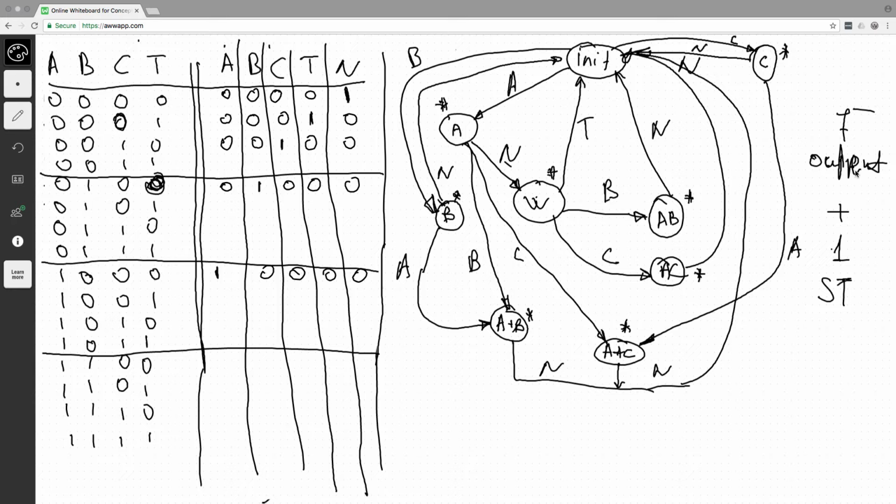And it actually depends on the implementation of the timer, because timer expiration bit can be considered permanent when timer is expired and it will stay in the expired state. So in other words, once we follow this route and the timer got expired, the timer remains expired, and in this case t will be 1.